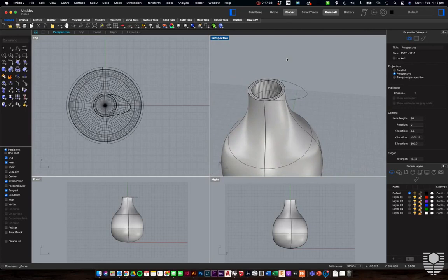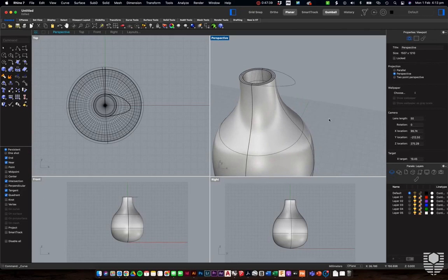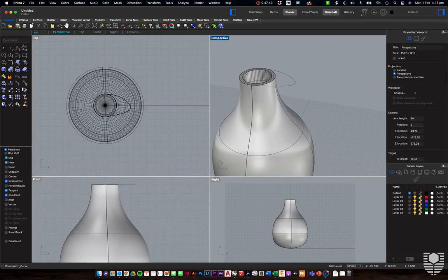So planar allows you to lock the plane that you're drawing in, and it kind of disables the stickiness of the construction plane momentarily for you. Another example, if we go onto the side here, so say if we've got that part of the spout, now we want to connect it back to the jug, we'll get another freeform curve.